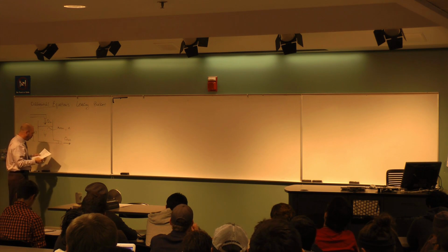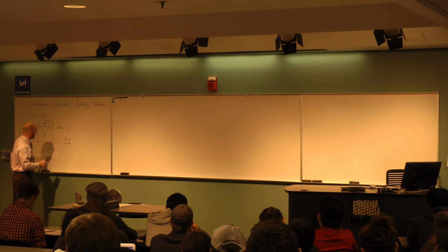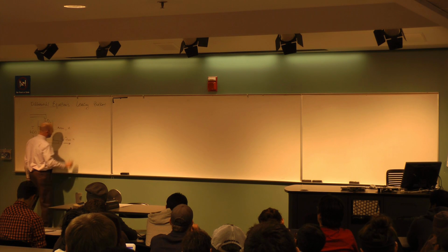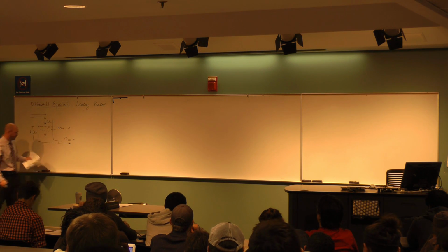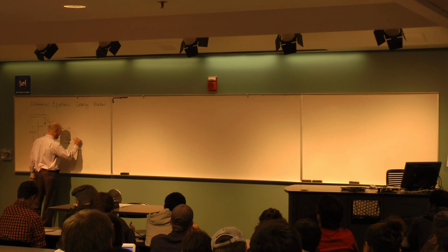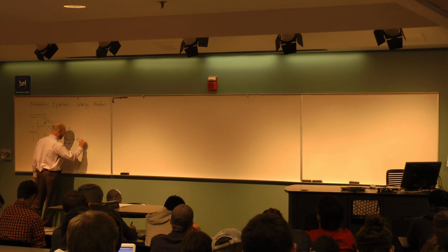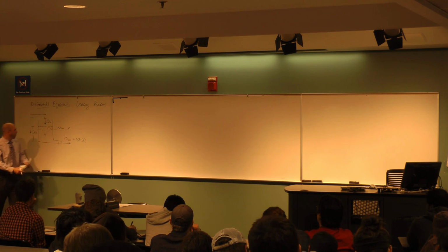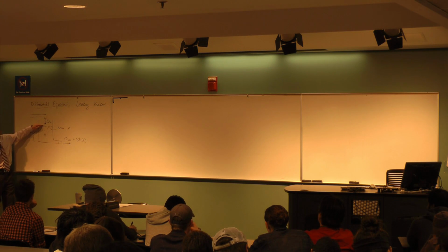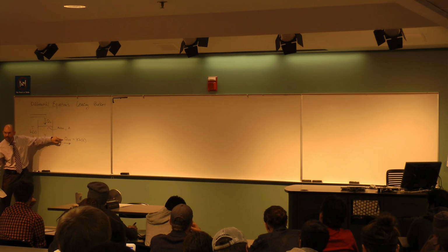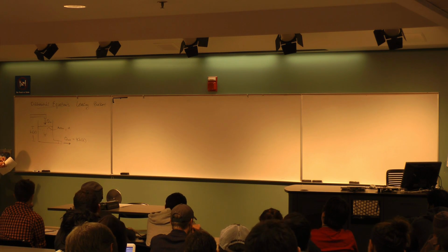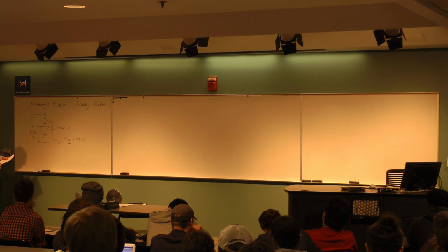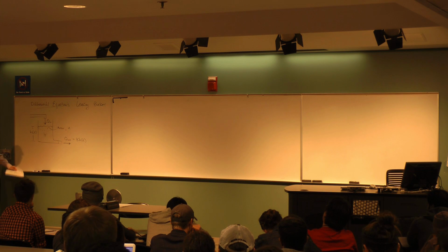Okay? And so what I'm going to do for this Q out is I'm going to say it's proportional to the height. And this is kind of a simplistic way to think about it. But I'm going to say it's some constant K times the height, times h of t. That way, the higher this thing gets, the more Q out I get, which makes some physical sense, right? Because of the extra pressure. All right, so we're getting there. Okay, what do you think that K depends on?